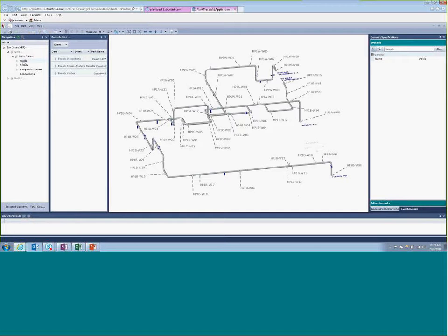So one of the things that SI does is we use this Vindex system, which is basically a risk-based prioritization that incorporates two things. It incorporates the Vindex, which is a vulnerability index, and essentially, in layman's terms, that's a score that gives you the likelihood of failure. It's the life fraction expended, and that's derived from a couple of things: the weld operating stress, the material type, the strength properties of that material, operating conditions, service history, any known industry issues, and any known material conditions from prior inspections.